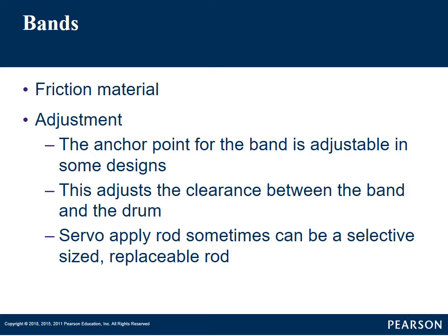The more clearance it has, the longer it takes to apply, which could lead to long and soft shifts. But if you have it too tight, it could drag and burn up the band, or it applies too quickly and you get a real harsh shift that the customer will complain about.